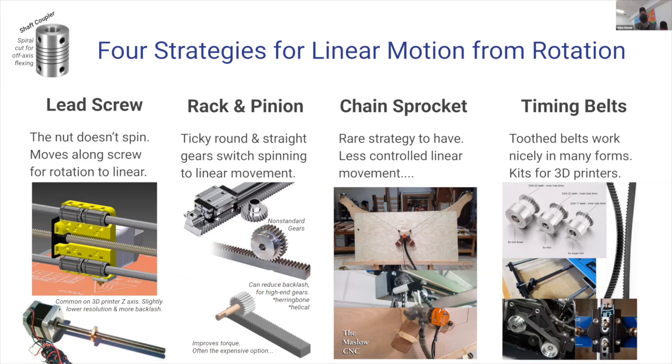And people have designed entire CNC machines. This is the Maslow CNC. You can see it's got basically a palm router that is held onto a thing with a couple of bricks mounted, so it's heavy. And then it's got 2 chains coming off the left and right. Then it uses polar math, like a weird math variation of coordinates, to be able to CNC just like the Gerber does. This was advertised for a while as the CNC you can hang up on the ceiling in your garage and then drop it down whenever you want to use it.